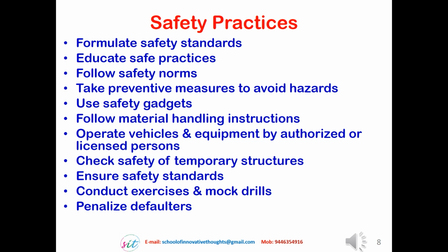Before use of the temporary structures, we should check the safety of the temporary structure by adopting a load test as well as physical inspection. Most of the accidents occurring at project sites are due to the failure of either scaffolding or shoring or formwork. So proper inspection should be carried out before using these temporary structures, especially the scaffolding and the formwork.